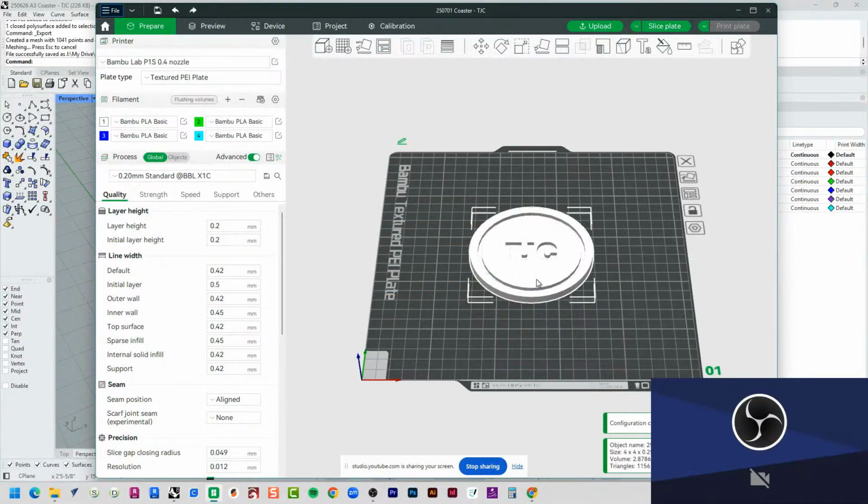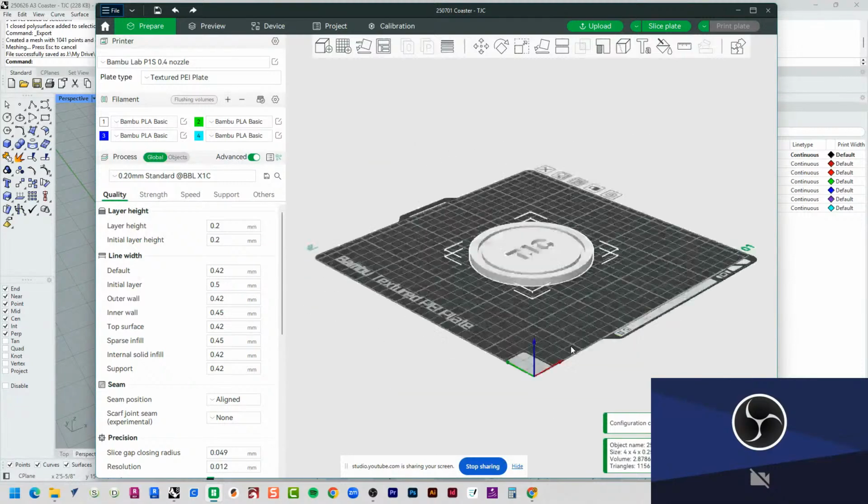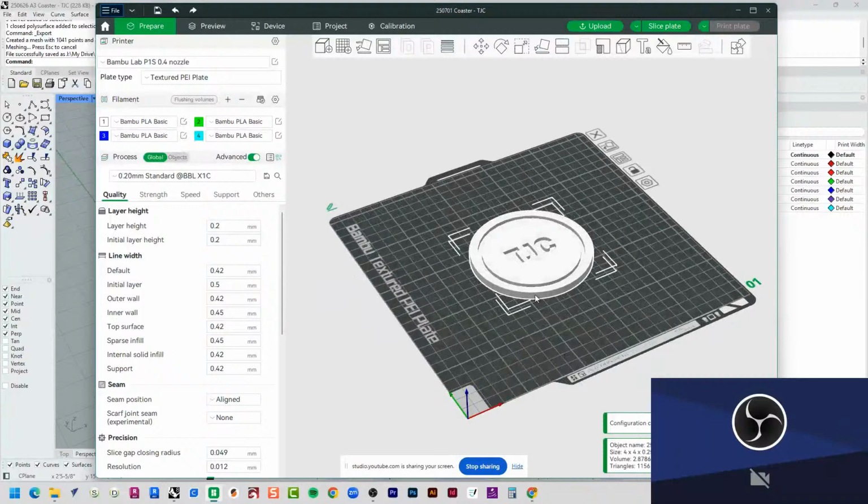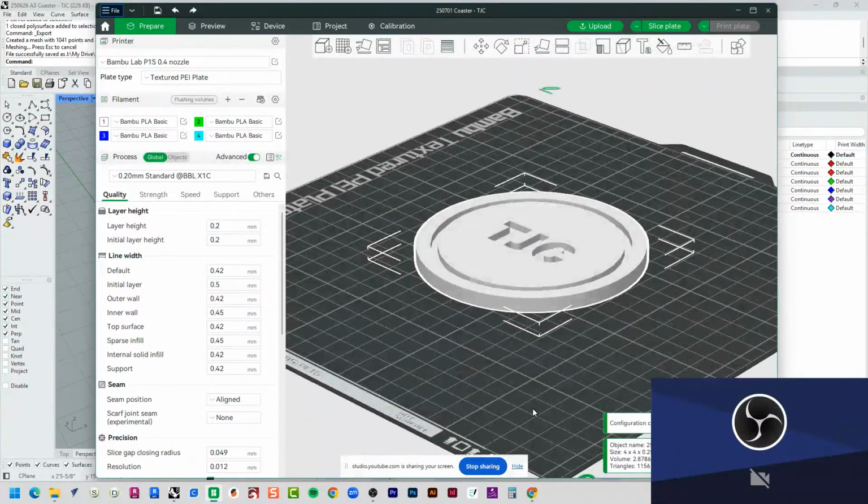Okay, so here's the difference already, right? Bambu Studio was smart enough to know that I probably didn't want to print out a coaster this big, right? It's like, I don't know, that looks pretty tiny, kind of a waste of time. Did you mean its equivalent in millimeters? Yes, I did. So right off the bat, as soon as I imported it, it's at the right scale. Okay. So when you encounter that, you want to make sure you say, yeah, please scale it up to millimeters. It was in inches.